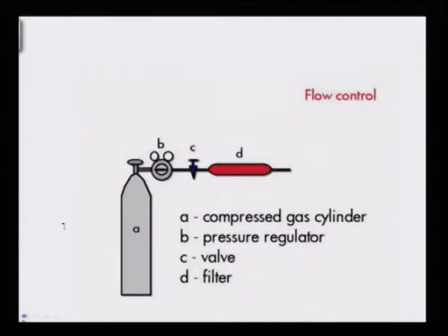Now, if I have to explain to you the different parts of the gas chromatographic machine, the first part which is very important is the gas flow, and obviously the gas cylinder must have a good regulator to control the gas flow. If the gas flow is very fast, all the components will be flushed out of the column and there will not be any separation process at all. If the gas flow is very slow, then the components will take hours to reach the detector.